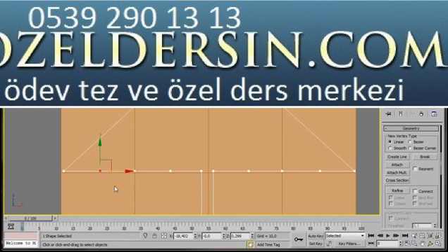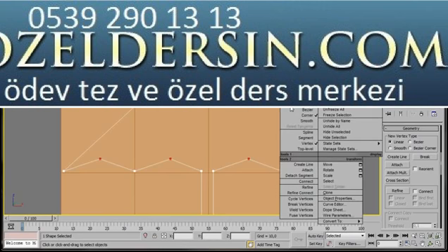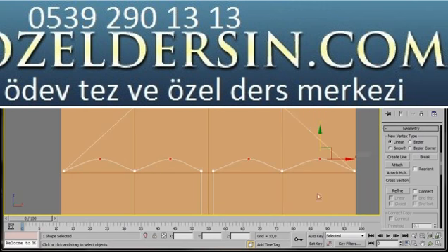Now I'm going to just select them, hold the Control key down and I'm going to select the other ones that I've made. There we are, I have all 4 selected. I'm just going to drag them up. They're a bit pointed. Let's see if we can change this. If I right click and from the menu, I have Bezier, corner and smooth. Notice these vertices are set to corner. I'm going to select smooth. There we are. That was easy. I can just move this up and down and make my curves larger.